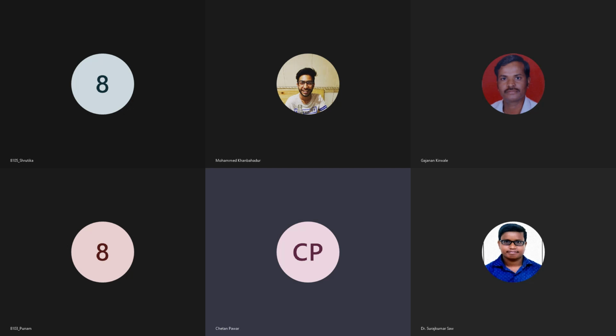Yeah, good. Escape. So now you take one V pulse source from analog lib. If you want to take any component, type I for instance. Analog lib, select the library.